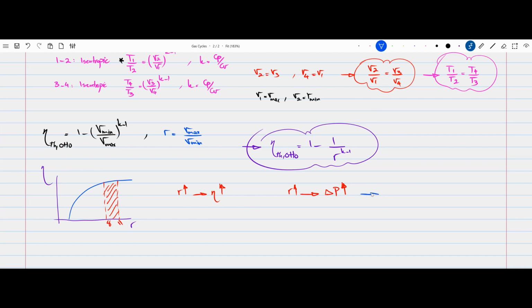This is a phenomenon that is sometimes referred to as engine knock. You might have heard of it. An engine knock is when a premature combustion happens within the cylinder. Because it is out of sync with the rest of the components in the engine, specifically the crankshaft, it causes wear and tear on the crankshaft, and it wears down the engine quite rapidly.